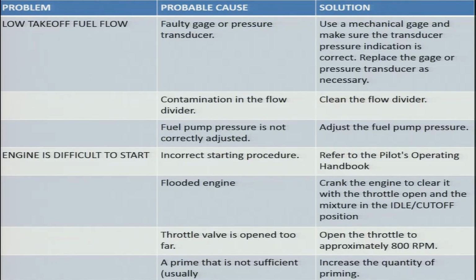So, there are several reasons for low takeoff fuel flow: a faulty gauge or pressure transducer, in which case the gauge or pressure transducer needs to be replaced; contamination in the flow divider, in which case the flow divider needs to be cleaned. Again, in the field we are not supposed to clean the flow divider. It should be sent to the respective service agency. Fuel pump pressure is not correctly adjusted. In that case, your fuel pump pressure should be adjusted according to the manufacturer's recommendation.